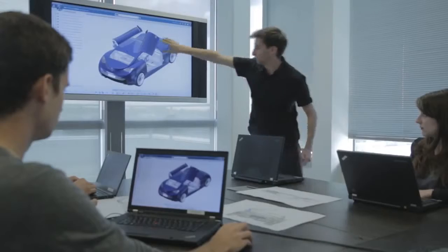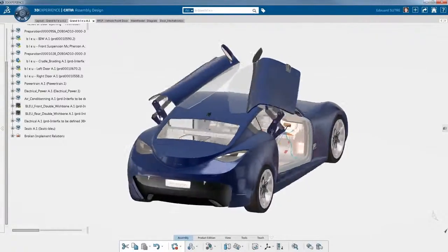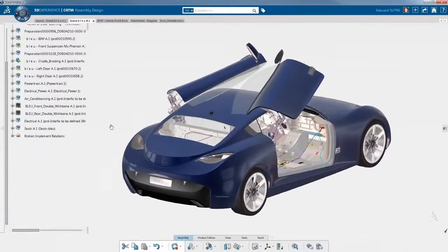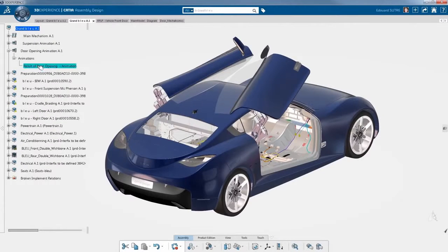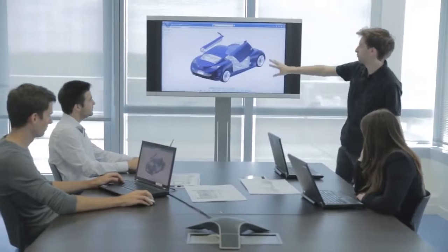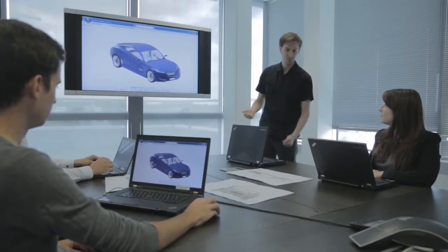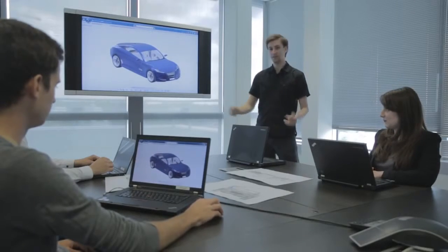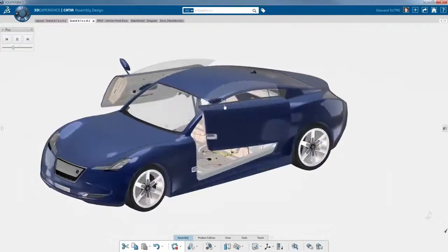So for this simulation, they just have to select the play button of the compass where all of the constraints of the assembly are directly reused for simulating the first level of kinematics movement. So here we are talking about mechanical simulation. It doesn't include how the speed of the system will go, it just shows you how the mechanism is behaving.